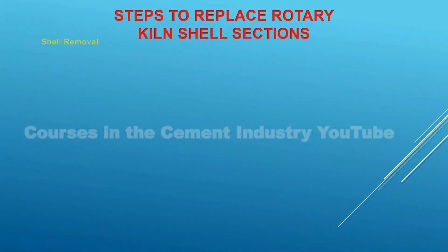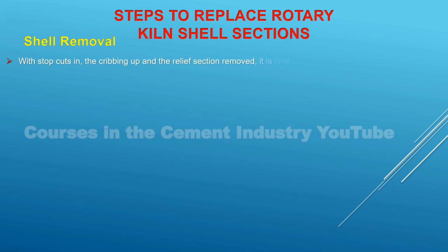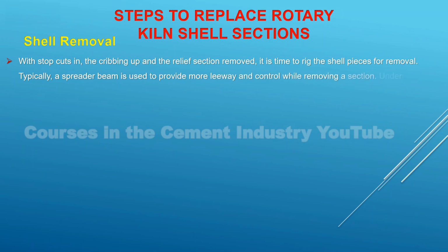2. Shell removal. With stop cuts in, the cribbing up, and the relief section removed, it is time to rig the shell pieces for removal. Typically, a spreader beam is used to provide more leeway and control while removing a section.